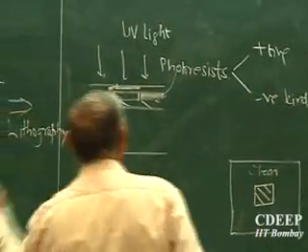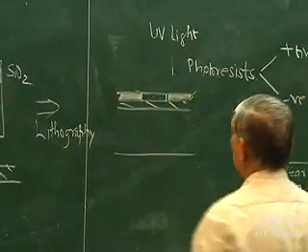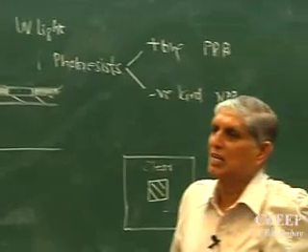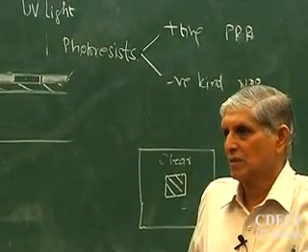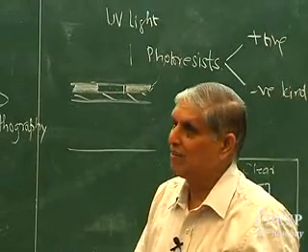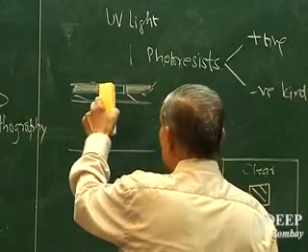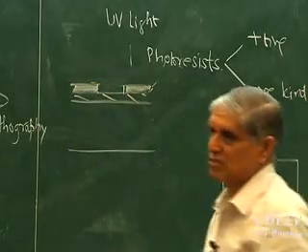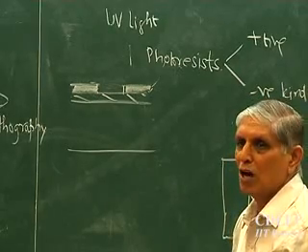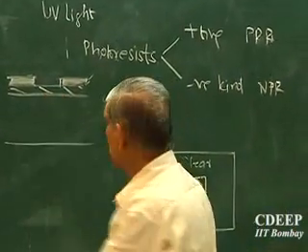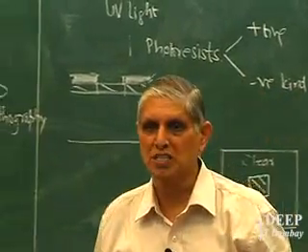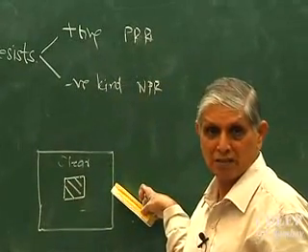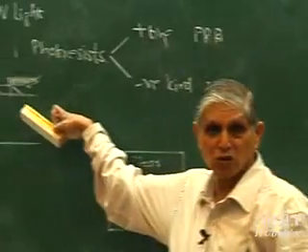Then I take away the mask plate, and I now have areas of oxide which are protected by hard resist and areas which are not protected, with soft photoresist. I develop this photoresist like in photography. This cannot be etched in the developer because it is hard, but the soft resist actually goes. It's developed. Is that correct? So now what do you see here? SiO2. In which areas is SiO2 exposed? This area. The rest of the silicon dioxide area is protected. This is cross-sectional, this is plan. Is that point clear? On the top you will see this, but in cross-section you will only see this.